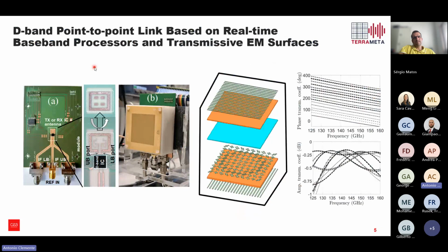in our demo today, we use a metasurface that is based on 3 metal layers. The full structure today is passive, and in order to control the phase, in the middle metal layer, we change the shape of the unit cell of the metasurface to control the phase. The question was, is it possible to generate a phase control in the middle layer by integrating an IC?